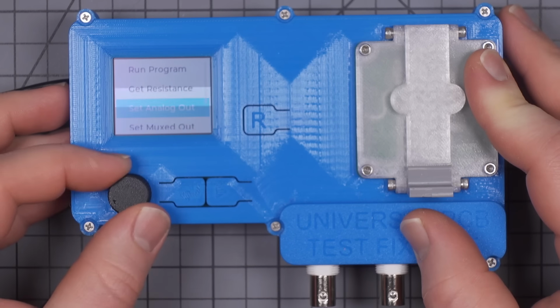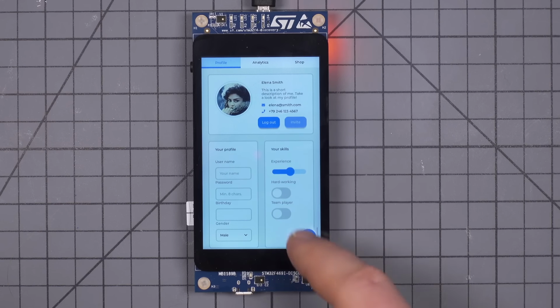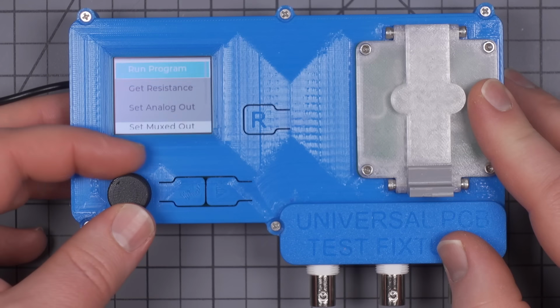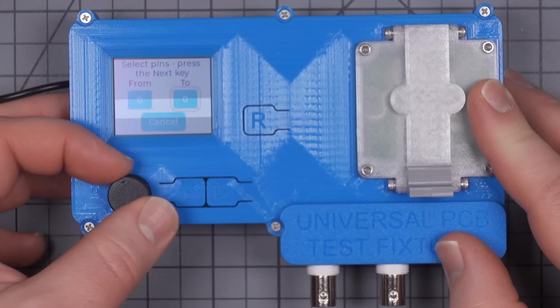Displays feed information to the user, but generally the user also needs to provide inputs to the microcontroller. This is often done with tactile controls, buttons and encoders, or a touchscreen. Integrating tactile input devices with a display is conceptually simple. Most commonly, you have up and down signals from buttons or the encoder, and an OK button, or clicking the encoder knob.